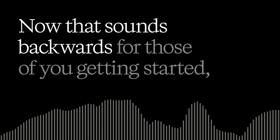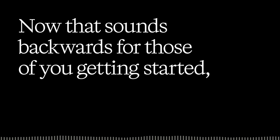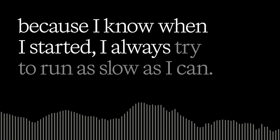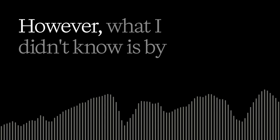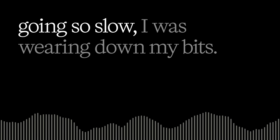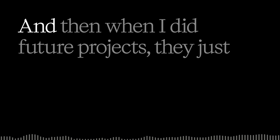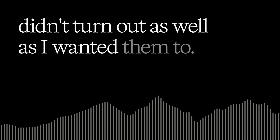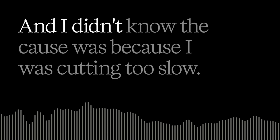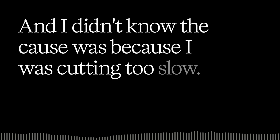Now that sounds backwards for those of you getting started, because I know when I started, I always tried to run as slow as I could. I wasn't concerned about how long it took. However, what I didn't know is by going so slow, I was wearing down my bits. And then when I did future projects, they just didn't turn out as well as I wanted them to. And I didn't know the cause was because I was cutting too slow.